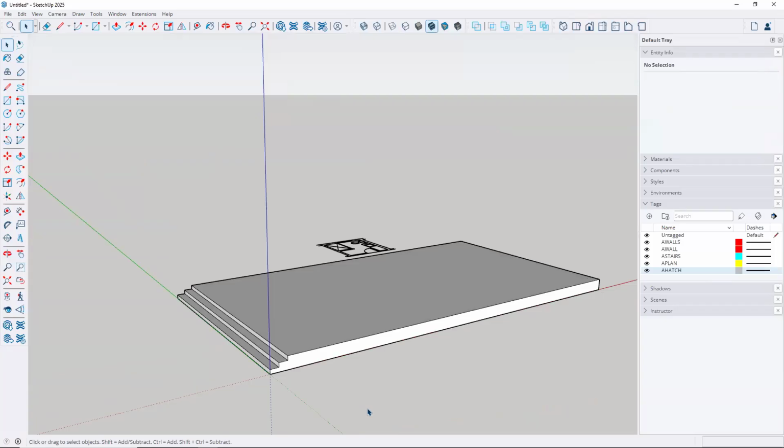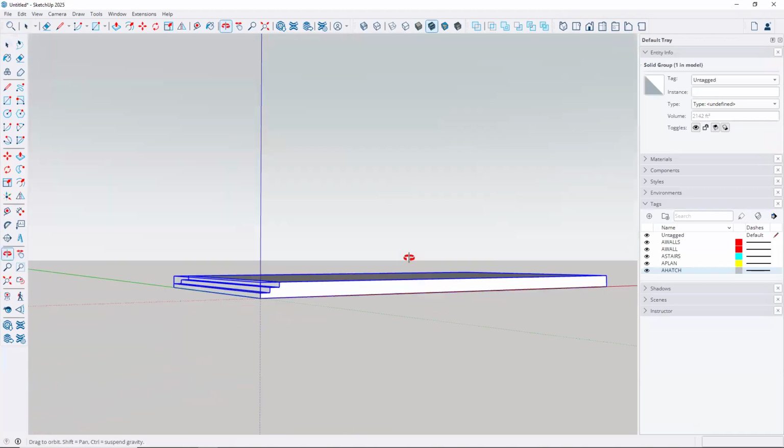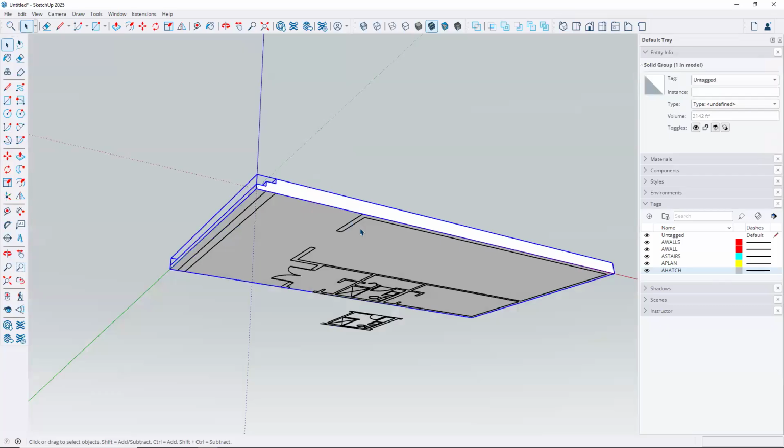And typical buildings here in Chicago, they're going to have basements, but we're not going to focus on that. We're just going to assume that this is the build up to my building, and then I'm just going to continue. So now I have this object in place, and I need to continue with my building, but you'll notice that my X-plan, my drawing file, is sitting below. So I need to be able to see through that. And the only way to do that is to move my building up. So I need to take this component and bring it up 18 inches.